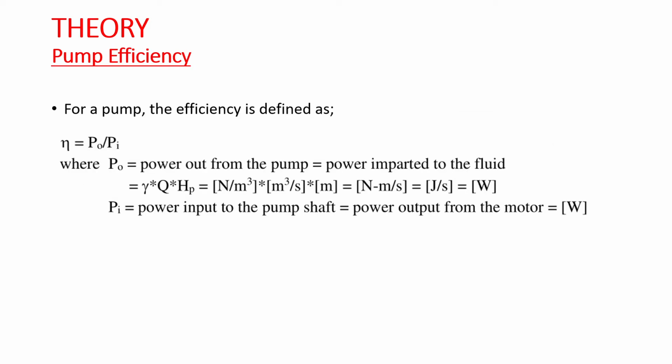For a pump, the efficiency can be found by this formula. Output power is determined experimentally. Input power should be given in the manufacturer's specifications for the pump. An important objective when selecting a pump for an engineering system is maximizing the efficiency for the desired flow conditions.